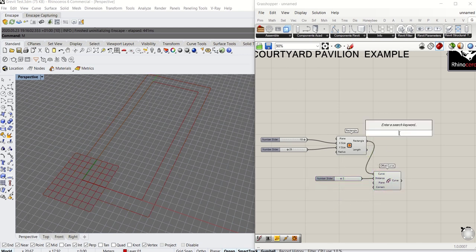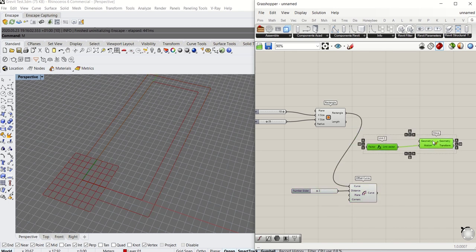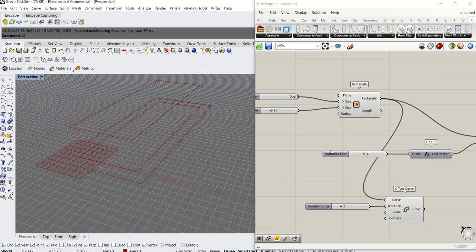And next you'll have to move these two lines up. First, we know the outer roof has to go slightly higher up. So you'll type move, give it a set vector, connect these two together, bring it slightly down to give a space, connect that to the rectangle and type 5, which will go up by 5 meters.